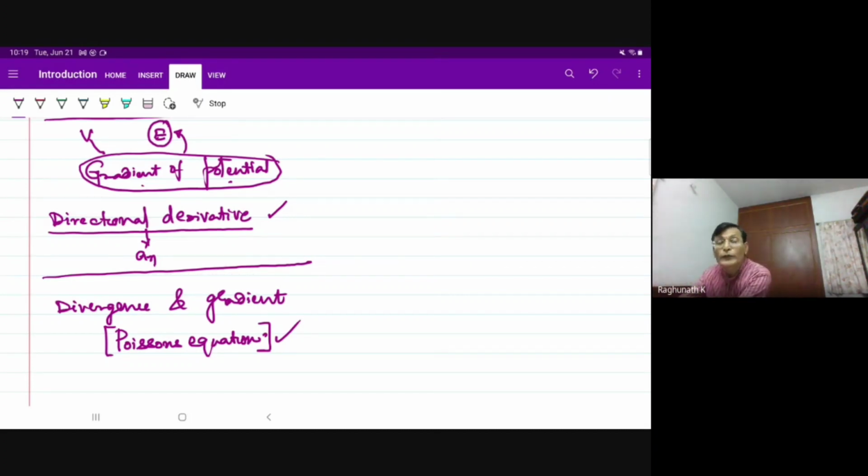I understood what potential difference of a junction is through Poisson's equation. Ultimately, one of the most wonderful, very high-level applications of diode is the variable capacitor. You vary the voltage, electronic tuning it is called. You vary the voltage, capacitance value will change. There are so many places where, to tune to a particular frequency, I should vary the capacitances. That's what we do whenever we tune a radio to a particular station.